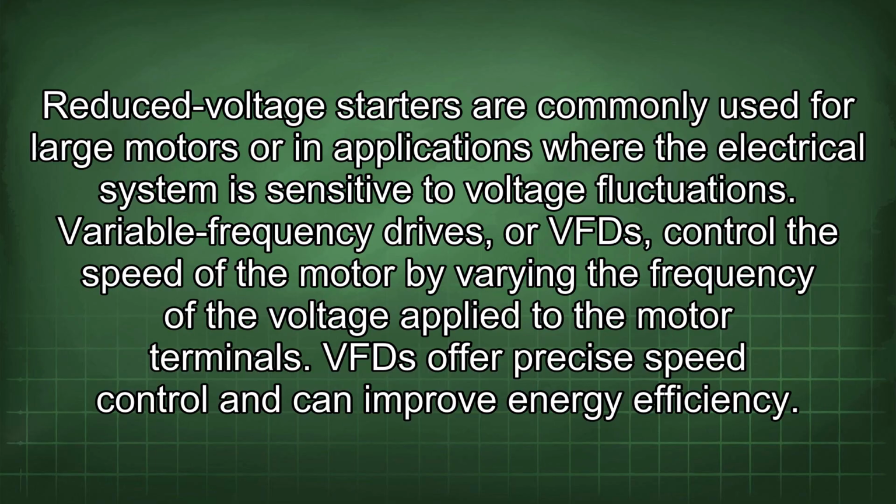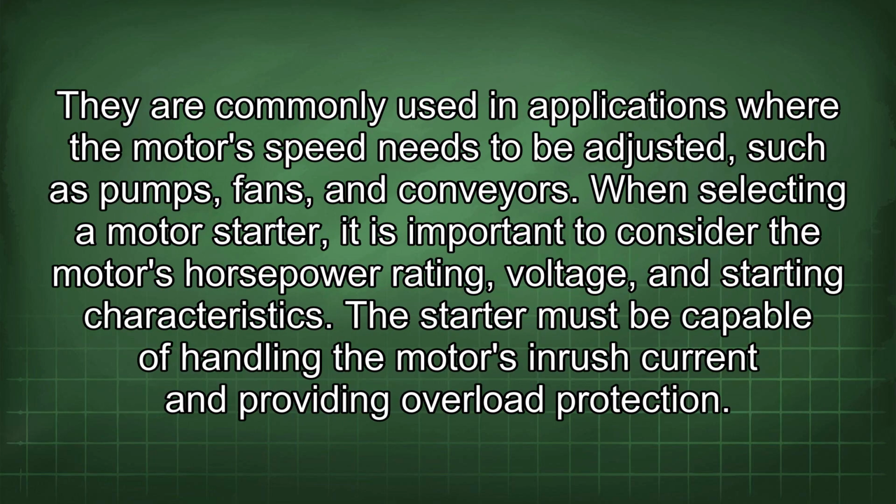Variable frequency drives, or VFDs, control the speed of the motor by varying the frequency of the voltage applied to the motor terminals. VFDs offer precise speed control and can improve energy efficiency. They are commonly used in applications where the motor speed needs to be adjusted, such as pumps, fans, and conveyors.